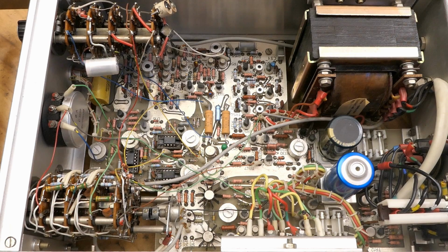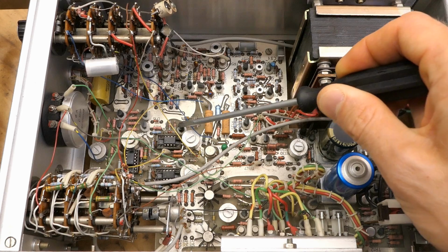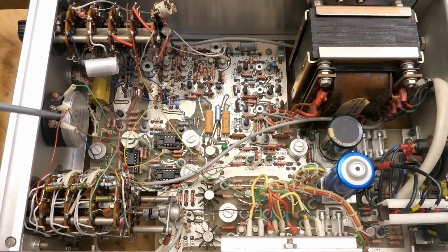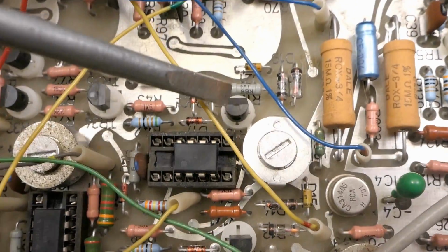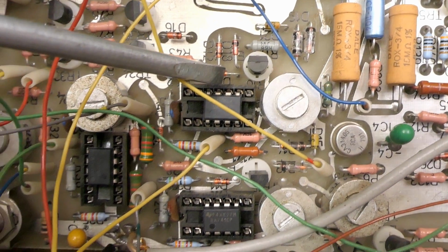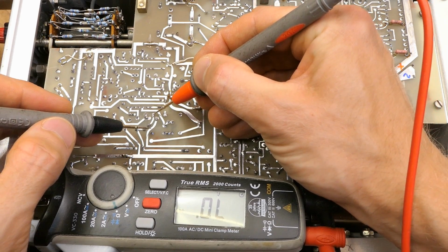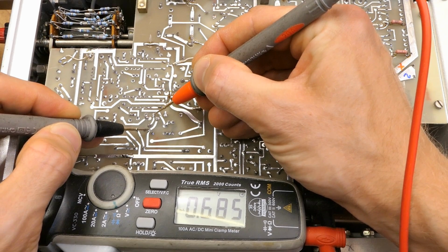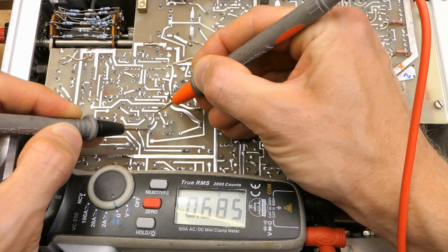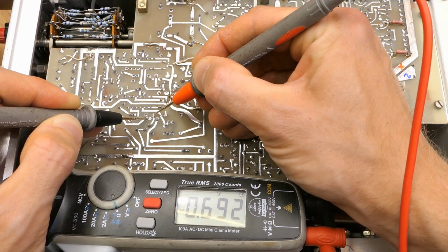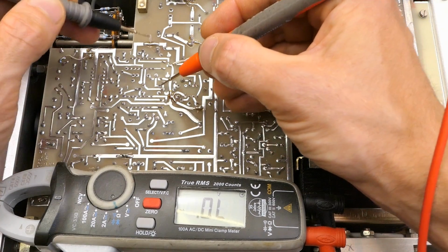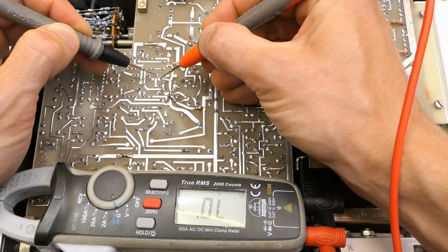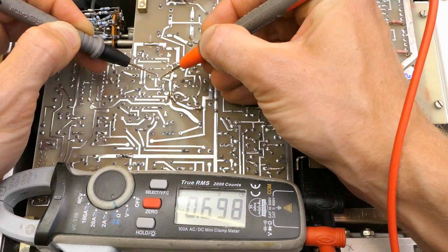After looking at the schematic and thinking about what could cause this specific problem, the most suspicious are these two transistors next to the op-amps. And the third one is the voltage inverter. A closer look, here is the transistor TR-15 and the transistor TR-16. Let's measure them on the other side of the board. This one is NPN, base to collector, 0.6 something volt voltage drop, nice. And the other junction base to emitter, again almost 0.7 volts, seems right. And the other one is PNP, collector to base, 0.6 something volts, seems right.